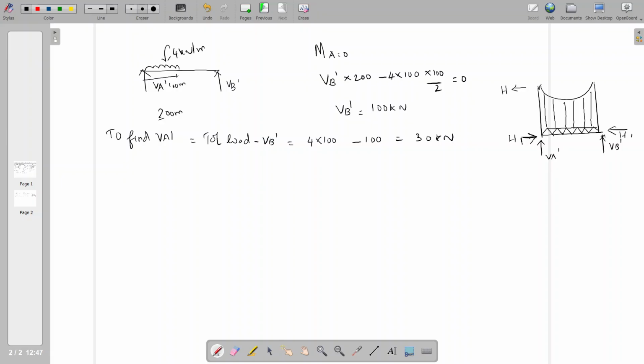So the inward force at the girder level will turn out in the outward direction at the cable level. If there is a difference of live load in the girder, then the reactions at the girder level and at the cable level in the horizontal direction will be different.